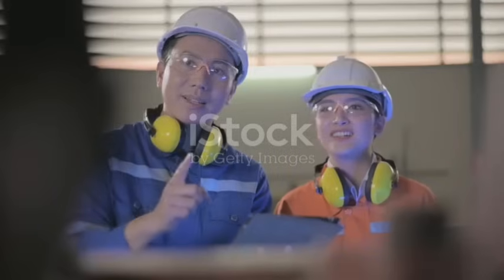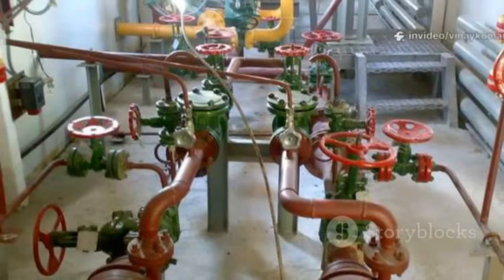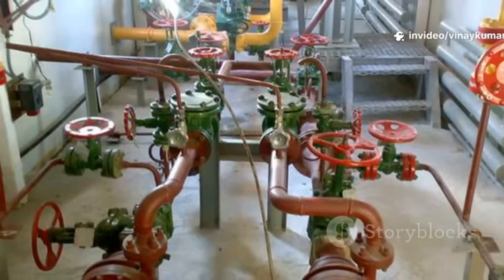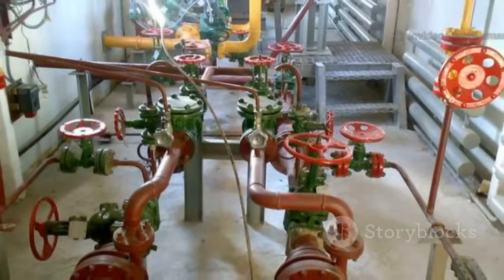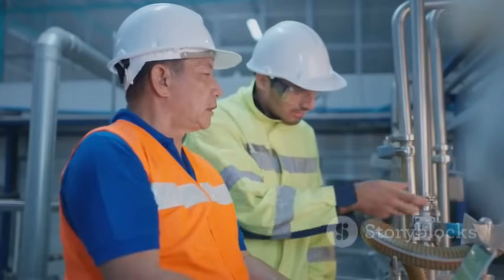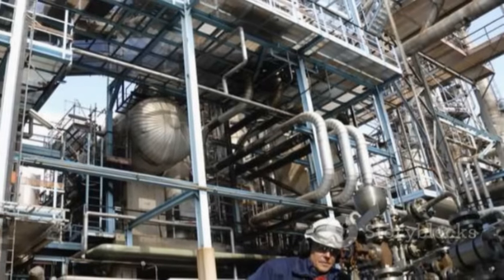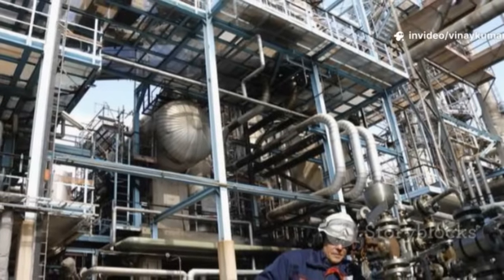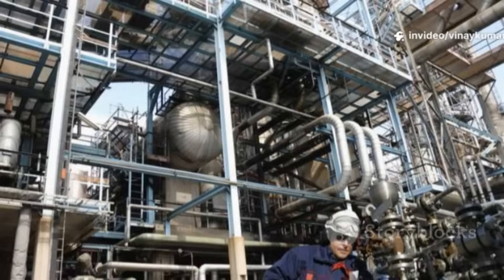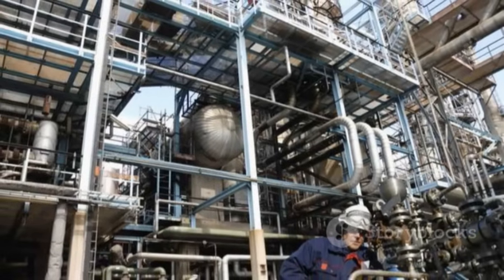So far, we've focused a lot on information, procedures, and people, but all of this relies on the physical equipment, the pipes, pumps, vessels, and valves, doing its job without failing. This is where our fifth element, mechanical integrity, comes in. The purpose of a mechanical integrity program is to ensure that equipment used to process, store, or handle highly hazardous chemicals is designed, installed, and maintained to minimize the risk of releases.